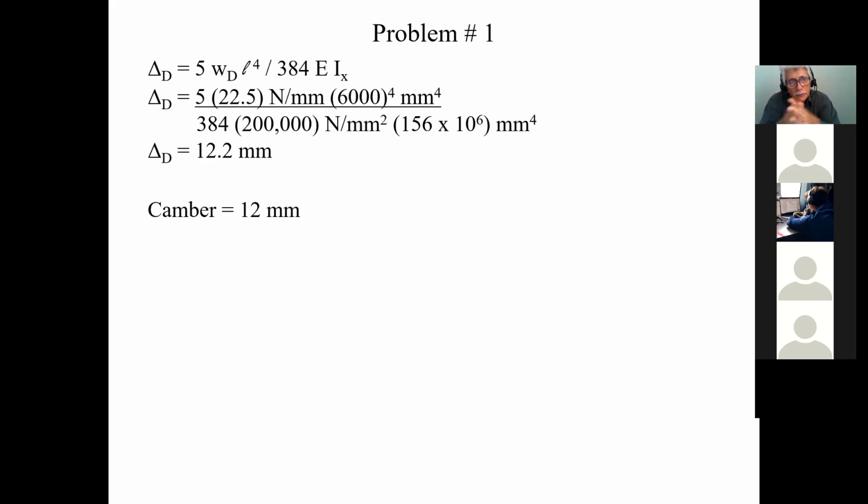The best thing is that I start with the MR, check the IX. If the IX is not strong enough, then I know I have to go up the table. I know that automatically my MR is going to be going up as well, so I'm only going to be that much safer in terms of strength. So that's what I like to do. Make sure my strength criteria is correct, and then after that, I check my serviceability. Many times the serviceability will actually force me to get an even higher MR. But if I can go down for my serviceability, I won't, because my MR is going to go down also. So I first worry about strength, then I check my serviceability, and then I make sure both have been satisfied.